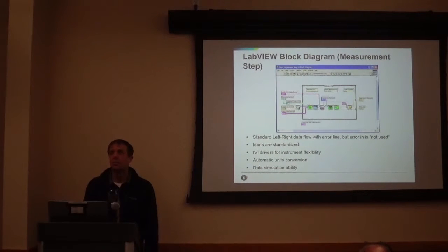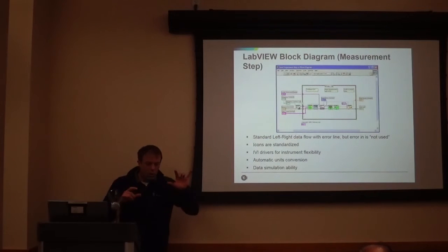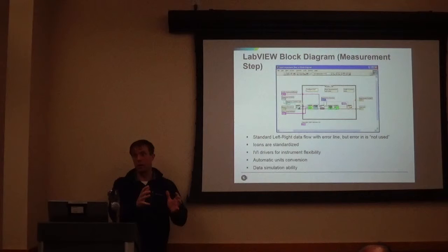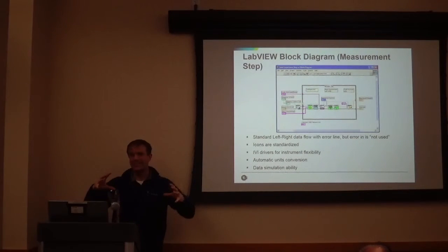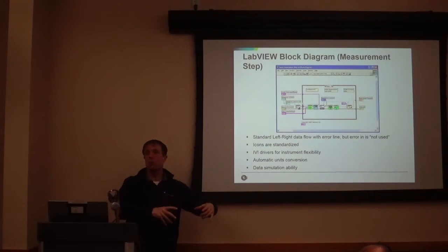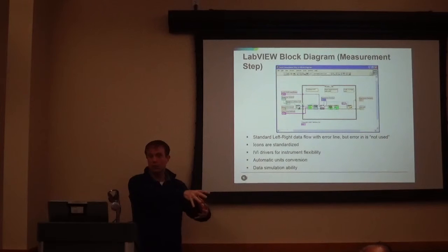You have to take all of your test modules and get those packaged in one way or another. Then you take your TestStand sequence file and save that. You're still going to be running a TestStand engine that opens the sequence file, which then calls all of your code modules in LabVIEW or whatever else.